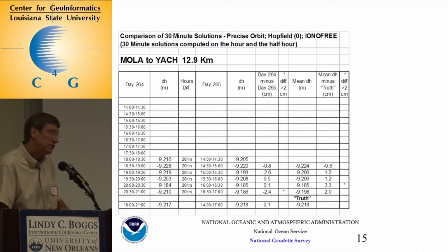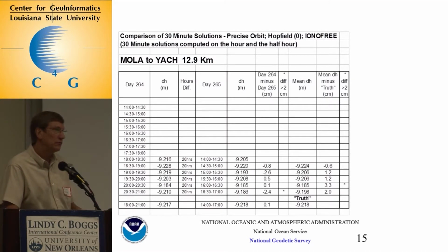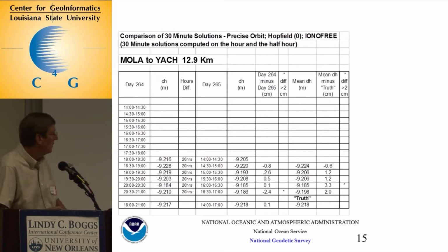One of our projects that we did was in California, where we spent 6 to 8 hours on sites to get good ellipsoid heights and orthometric. We knew that would give us the right good values. But we took that data, because it was a project, and we broke it up. Basically, this is just 2 days of data, and we broke it up into 30-minute segments.